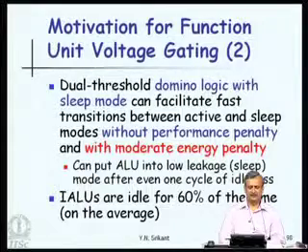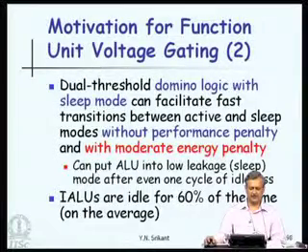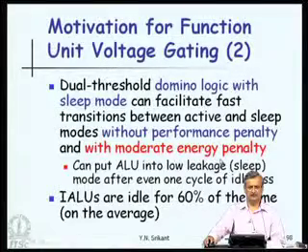But the nice thing about these dual threshold domino logic circuits is they can actually switch between these active and sleep states with very little performance penalty and very moderate energy penalty. Observe the words, there is not much performance penalty, because we are going to switch within one cycle. So, active to low is one cycle, low to active is another cycle, but if the switching is very frequent, energy consumption becomes high. So, there is moderate energy penalty for such switching.